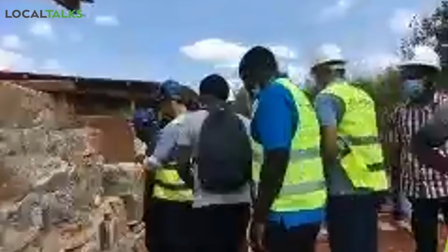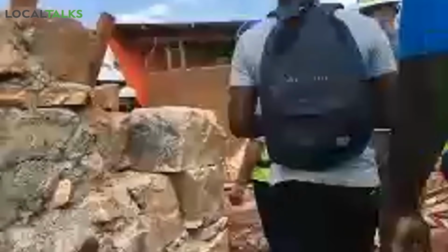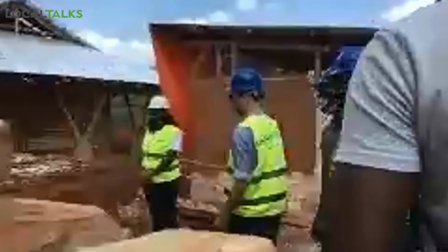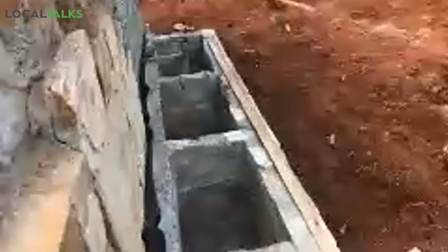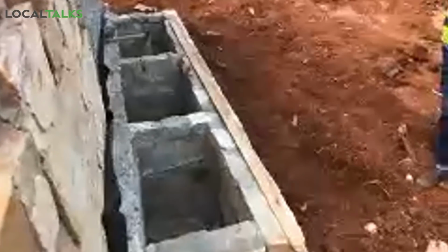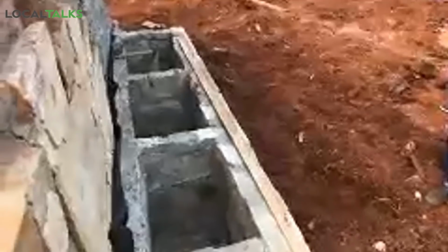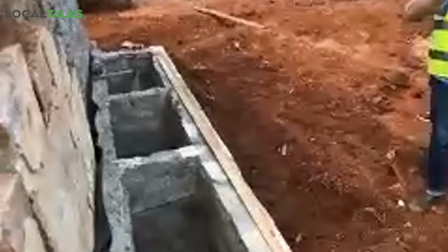The hand washing is only in the two left compartments, and the one on the right is the flushing tank. What we are doing here is that all the gray water from hand washing is collected in this holding tank, and then there's a flushing mechanism that can be pulled twice or thrice a day, and that will push the water through the main collection pipe and flush the waste down the hill.